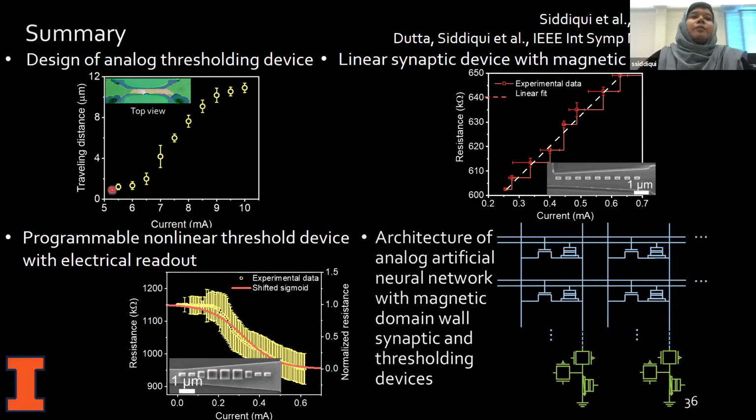So that's why we have this width, which is higher on the two sides, so that we can move the domain wall slower. But in the center, we want to create this ramp, which is very fast with the current density. So that's why we narrow down the width of the wire. In this particular case the wire is only platinum, but on top, where the domain wall actually is, the width of the ferromagnetic layer is constant. Oh, okay. I see.